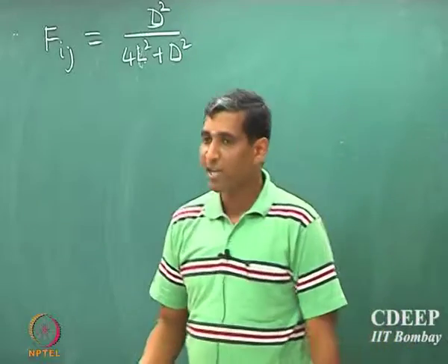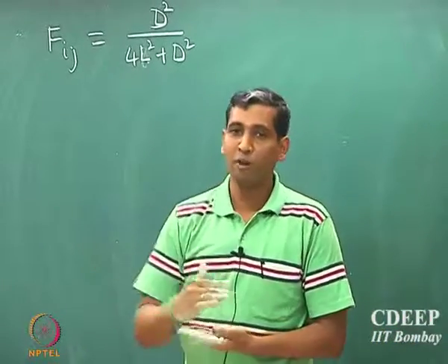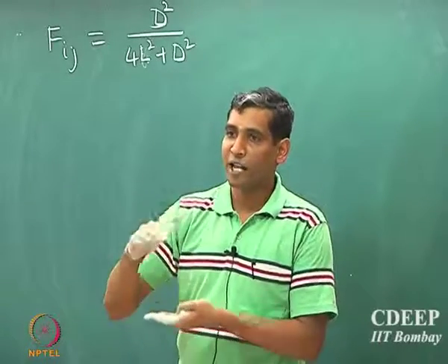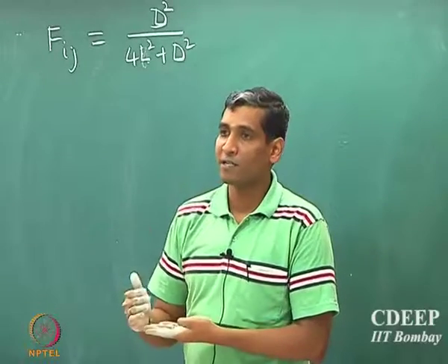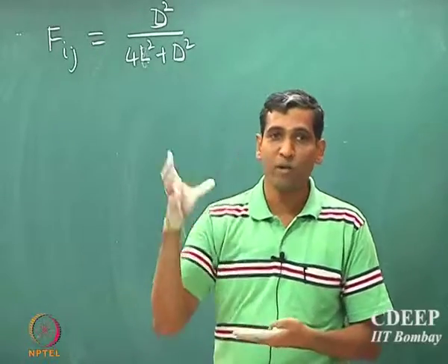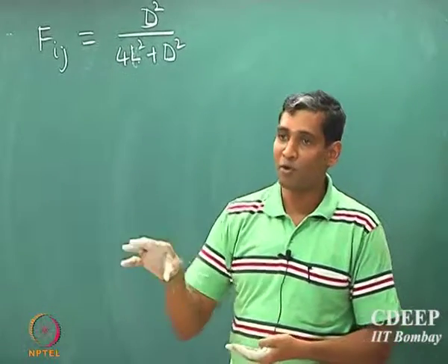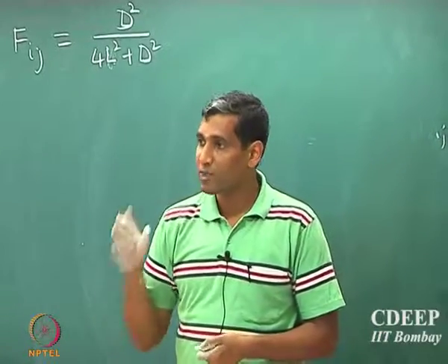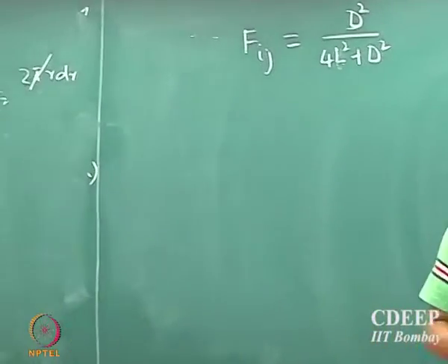So I really encourage you to take different examples from your textbook. In fact, there are tables in your book which tell you the view factor for different shape geometries, and you should really attempt to derive these view factors and convince yourself that you are able to construct the geometries properly. All the expressions given in the book are right, so you should be able to derive them. It is very important to learn how to construct the 3-dimensional angles and 3-dimensional geometries.